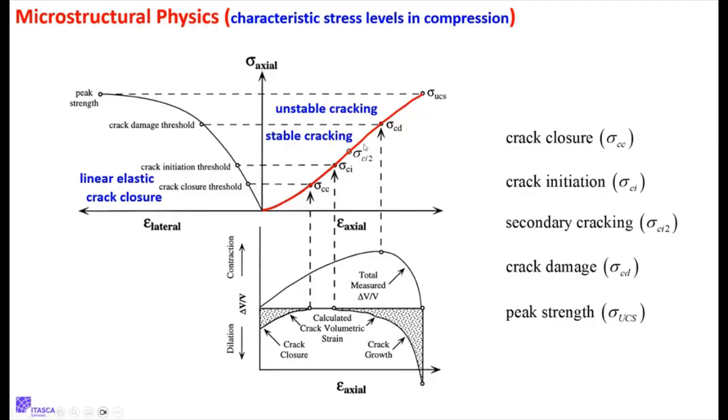So you keep loading this, and now's when it gets exciting. I've sat there with the grad student who's doing the test. I've never got to do tests, but I've got to watch some. And now it's getting exciting because for this 10-minute period, it's pretty cool. Boom, boom. Nothing happens. Then pop, pop. You hear little cracks happening. Sometimes little pieces of the surface go flying off. And this is called stable cracking because I could stop the test and unload it and everything. I could stop the test and hold the load constant and nothing would happen. It would just sit there.